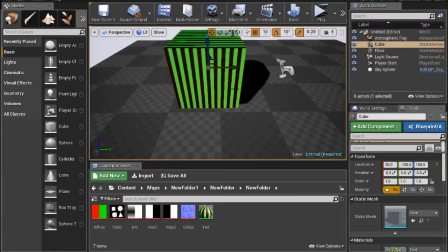For what can you use that? If you have a neutral object that has a texture you want to have, but the texture is way too big, you can use it very simply like this. As an example, a brick wall or something like that. So you can put the texture over the brick wall and then use the texture coordinate to find the right size so it looks good in your game.